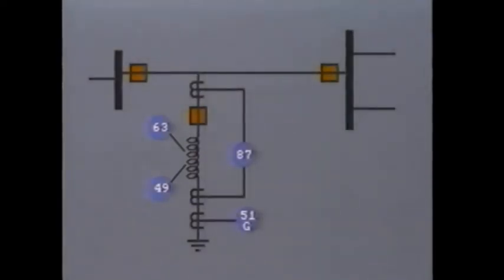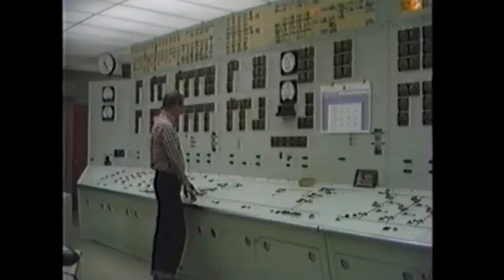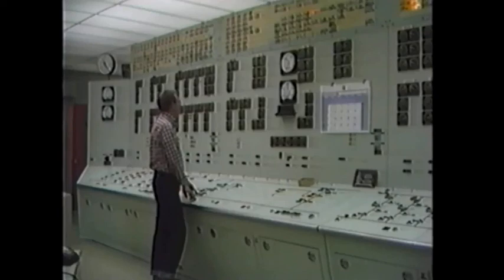Often reactors are connected directly to the line or bus with no breaker. Therefore, operation of reactor protection means that all remote breakers feeding the reactor must be opened. Once the reactor has been isolated by disconnects, the breakers can then be reclosed, but the system operator may have to take other steps to hold the voltage down.